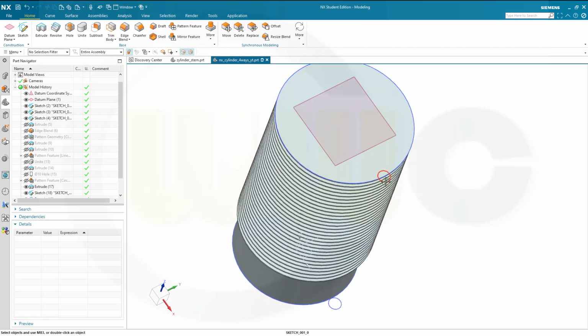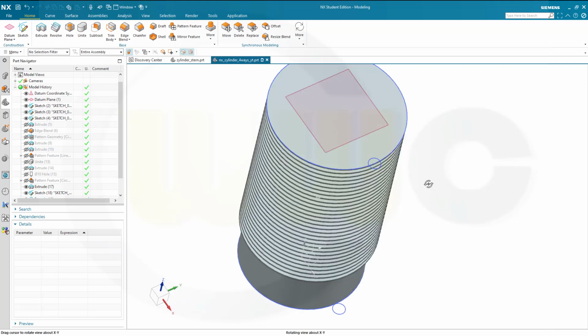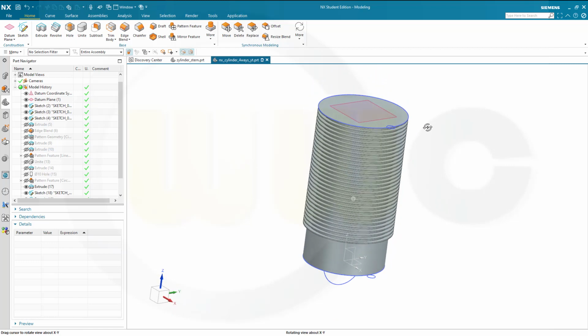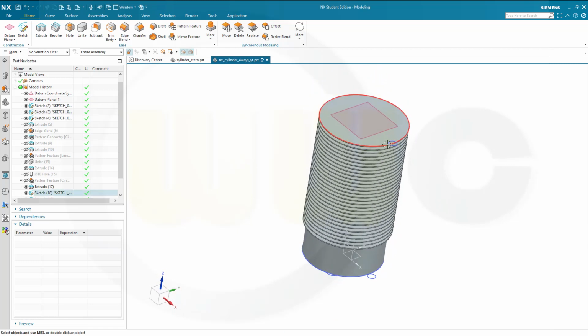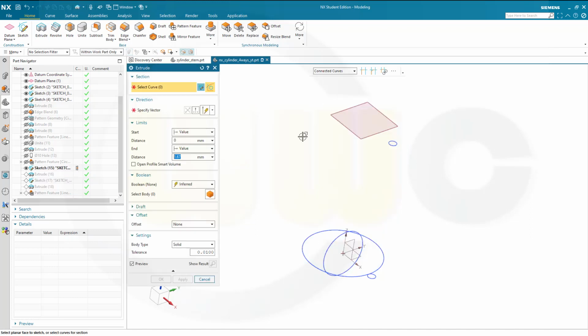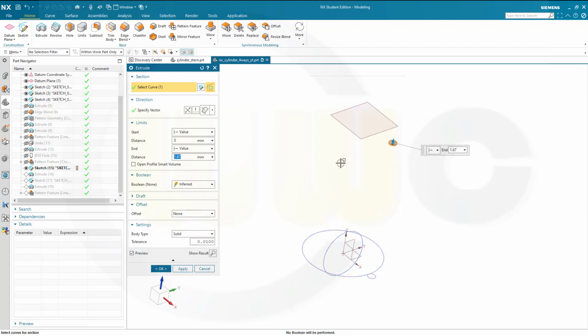Now I've changed the distance with my first method, so that's not necessary, but in order to make the round or blend, this has to happen before all the other stuff. So let's move that sketch before this extrude. Go here, make this the current feature, make an extrude with this one here.